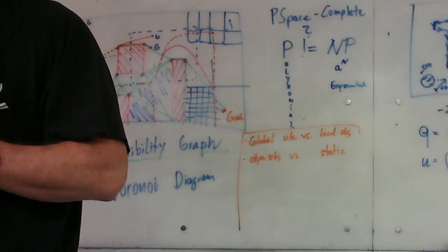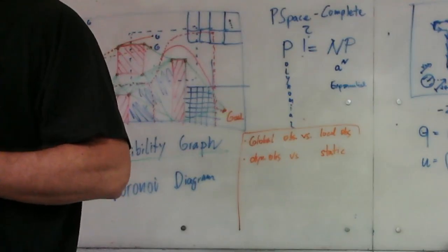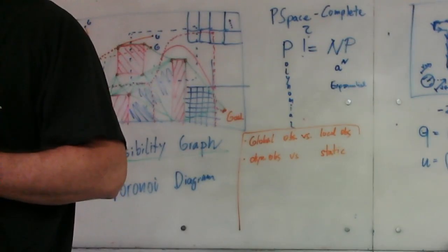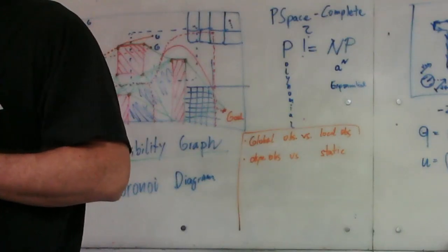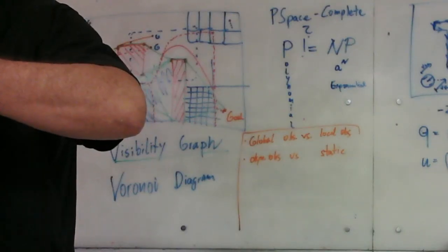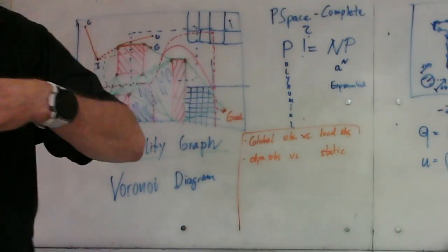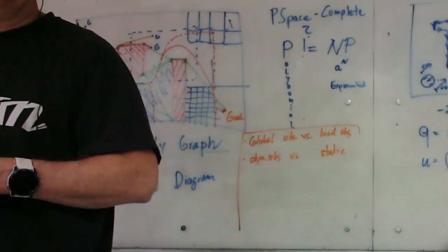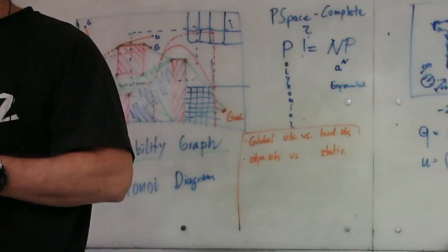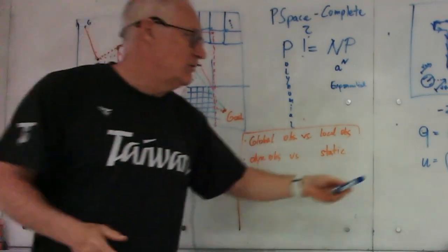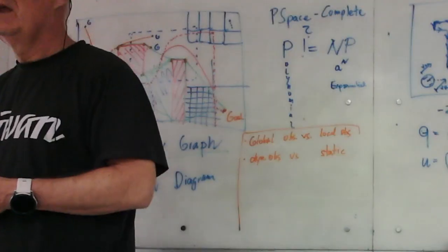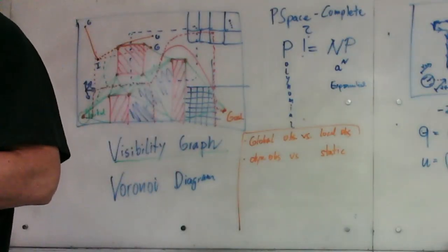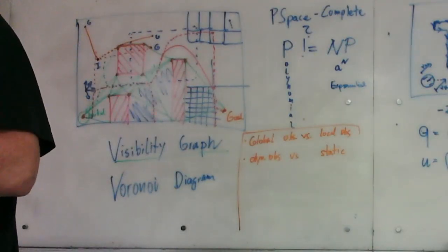Under what condition does the position not change? If they're equal and opposite, then the robot will turn on the spot. Right? So in that case, X and Y will not change. Any way in which I can make any of the other variables not change?